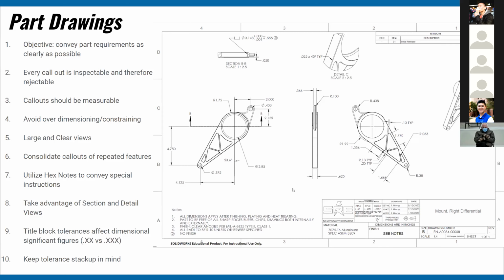Typically, I would say plus or minus 0.03 is a decent, not high tolerance dimension. 0.06 is super relaxed as well. That basically means you have an eighth inch of play in your dimension. But when you go into a three-place dimension, the more precision you have means more cost.